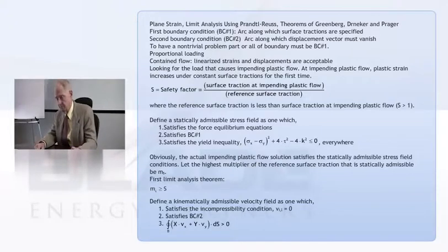Well, if you find such a stress field, then you can multiply whatever stresses you've just figured out by some number, and what any reasonable person would do is edge that multiplier up until they got yielding at at least one point.